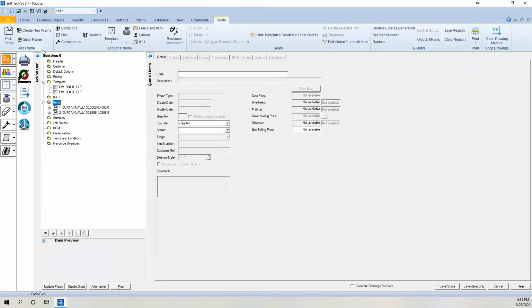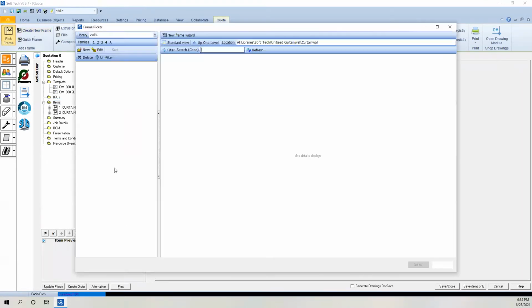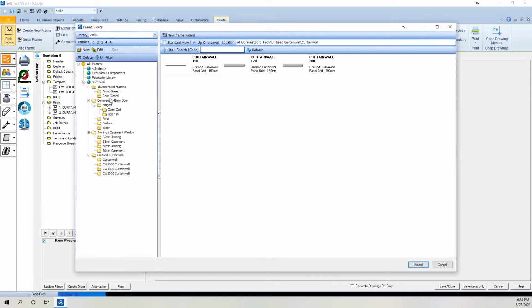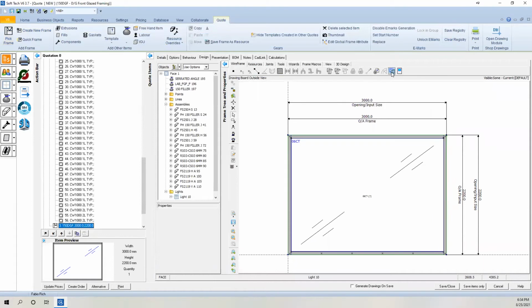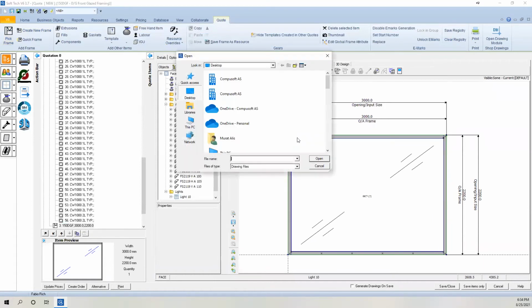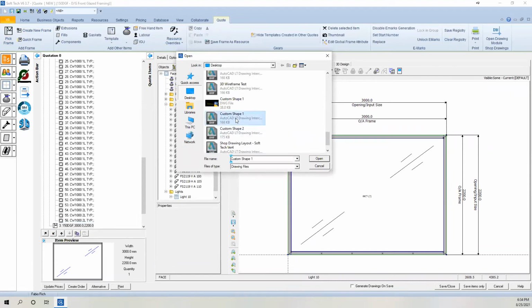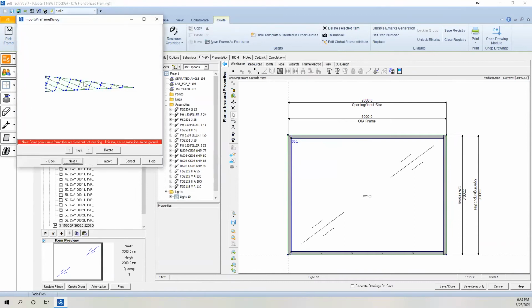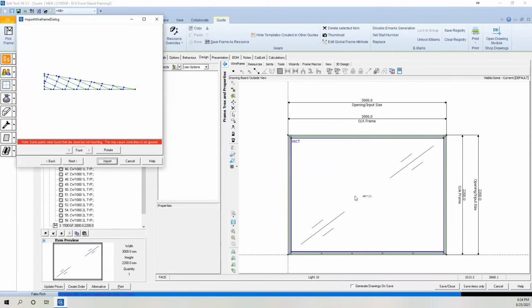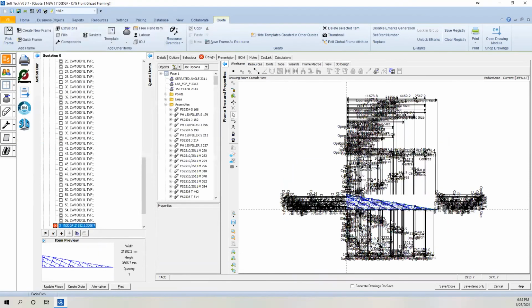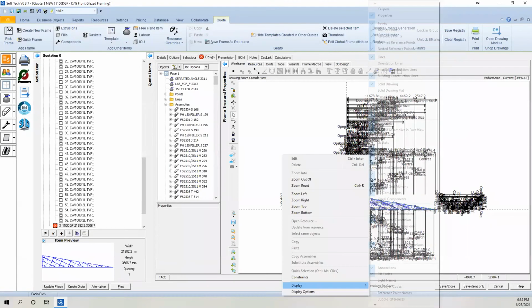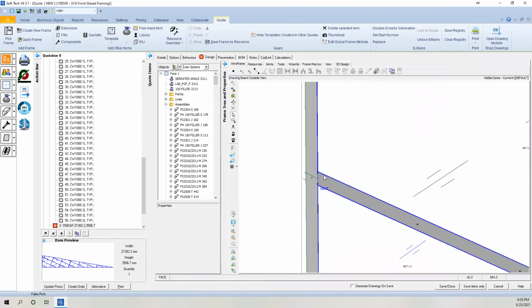So if I bring one more custom elevation, this is going to be a storefront. So I go and pick my storefront frame, then go to wireframe. And again, I bring a custom shape here. So click that button. And from this list, I'm going to bring that custom shape 1. Next, this is the shape. Import. And I will hide the annotation. So it looks like this.